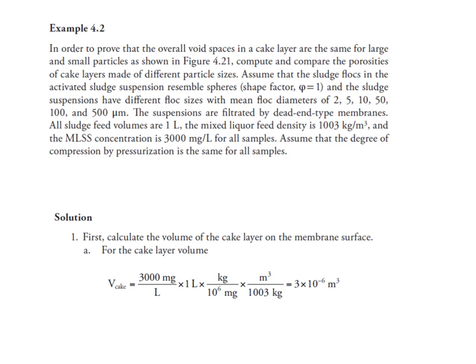Here we have a very interesting example showing how we can calculate the cake layer resistance, porosity and other cake properties. In this case, we just wanted to compute and compare the porosity of cake layers made of different particle sizes.